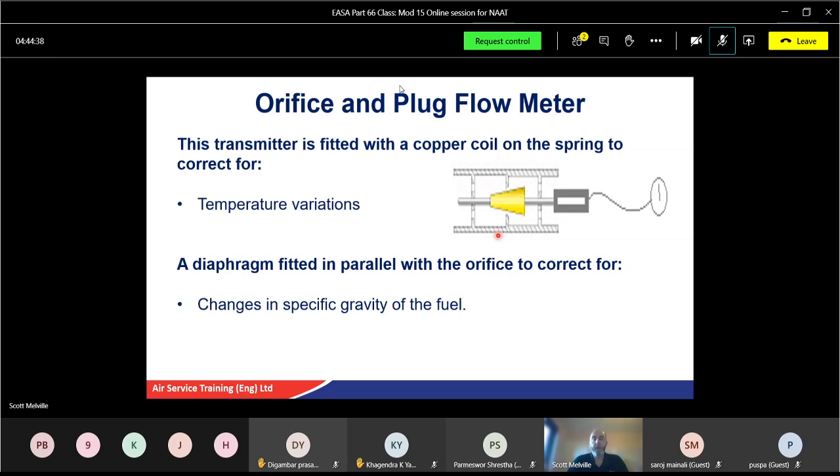To give an example or a parable, go back to my cars again. If you have your standard wheels on your car and you're reading 30 miles per hour or 30 kilometers an hour, that's fine. If you go and put a bigger wheel on, say you went from a 14-inch wheel up to about an 18-inch wheel, well, you'll actually be going faster than what the indicator's reading, because it takes longer for that wheel to do one revolution.